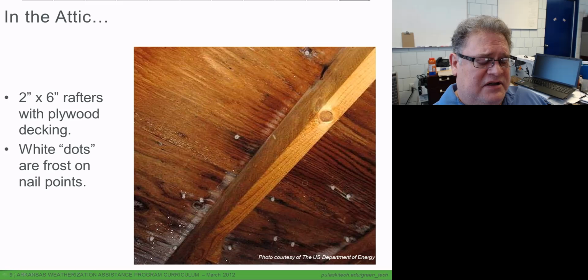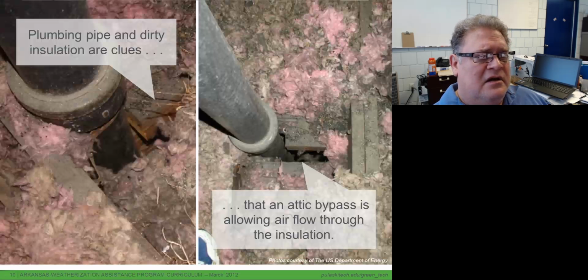We have saturation here, so we're getting condensation on the wood. Moisture doesn't really like to condense on wood until the wood becomes saturated. That can happen in the winter when you have roof decking over a hole that's leaking warm, moist air all the time. So in the areas where it's not saturated yet, then it's not condensing very heavily.